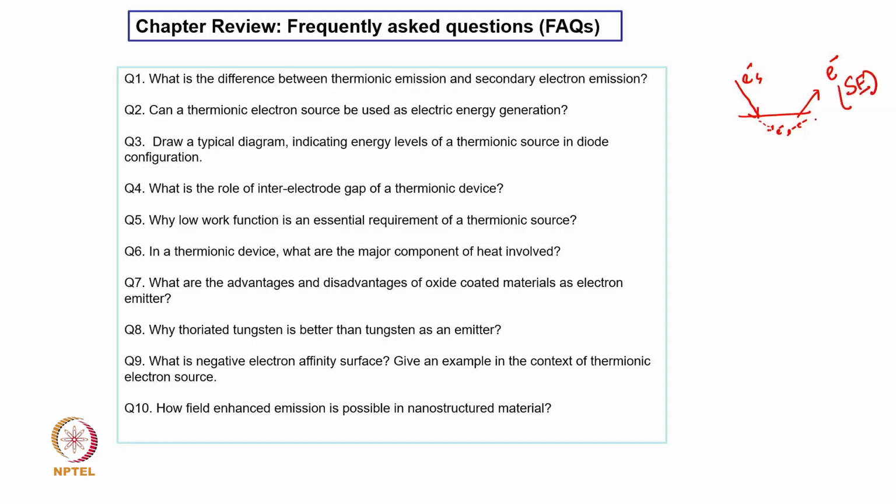Okay, that is called secondary electron emission. So, you need a primary electron before you generate a secondary electron, and this primary electron interacts with the material close to the surface and generates secondary electrons which are emitted, and this is the technique which is used for SEM.